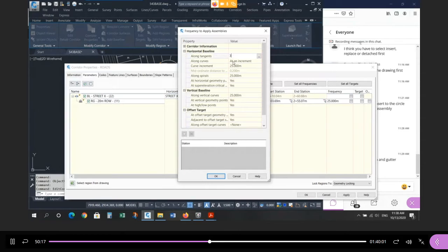On all the different curve types, okay, so our horizontal curve, a circular curve, I'm going to go every 1 meter. On a spiral, we don't have any, but I'm going to go every 1 meter. So the horizontal, circular curve, and spiral curve, if I have one, I want a cross section every meter. And then if I have a vertical curve, which we're not going to have any, but if I had a vertical curve, I'd want to do the same in the vertical. But if I have a circular curve or a spiral curve or a vertical curve, I want a cross section every meter. And it will continue to build the surface of the road with straight lines.